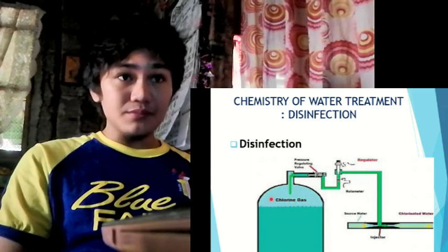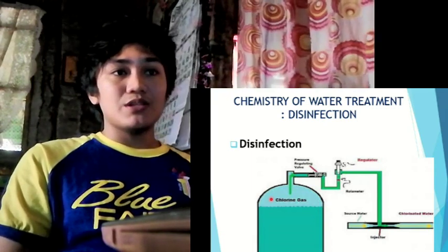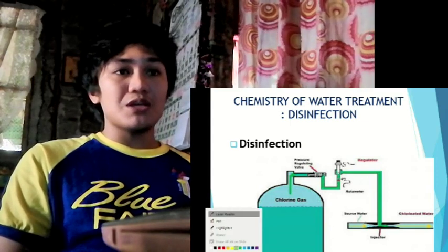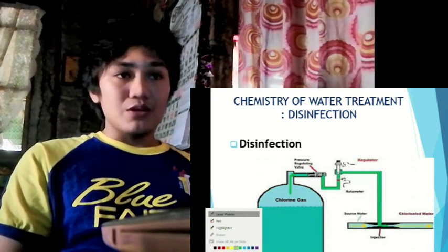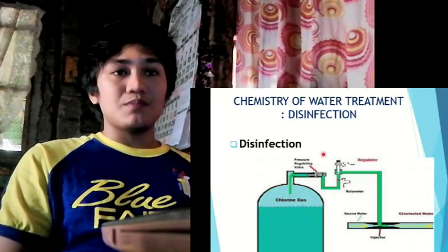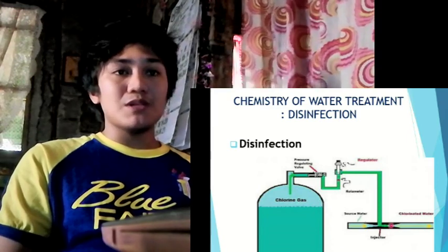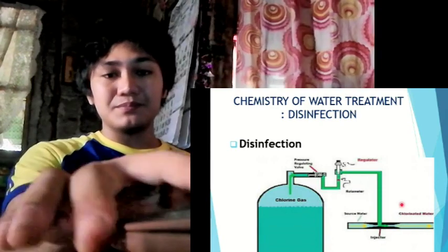Sixth, they must persist within disinfected water in a sufficient concentration to provide reasonable residual protection against its possible recontamination, because this is not normally an attainable property. The disappearance of residuals must be a warning that recontamination may have taken place.